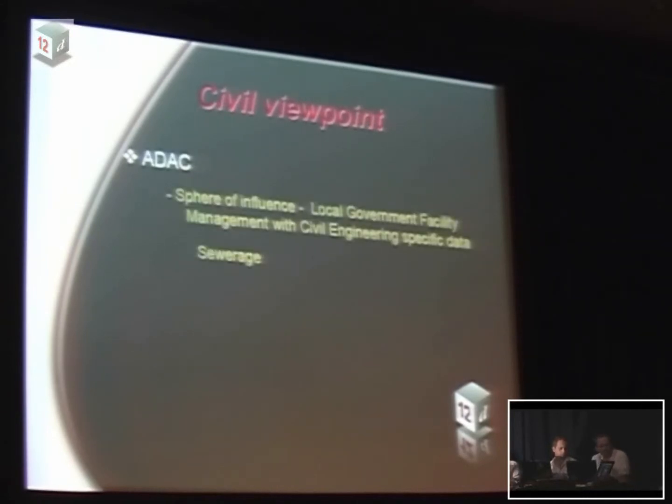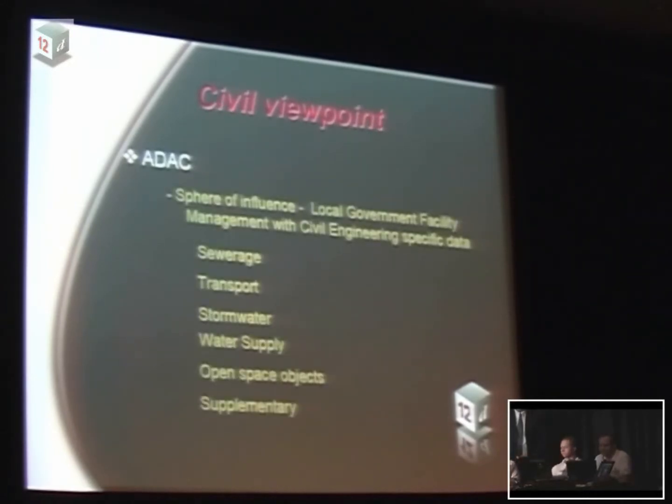In southeast Queensland, there is a system in place, or it's being trialled by some councils or actually running in others, called ADAC, and its viewpoint is from the local government, facilities management. So they also have their limited view of the world. They don't store alignment geometry and things like that, and so therefore it's not the be-all and end-all, I don't think, for everybody. But they are very good at storing information like services, that sort of thing. So your Dial Before You Dig, all those kinds of things will probably end up in this kind of structure.